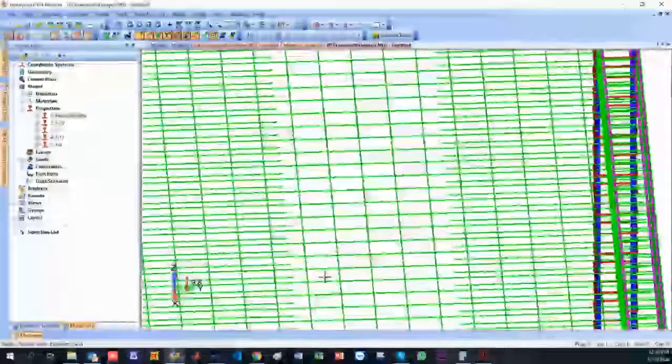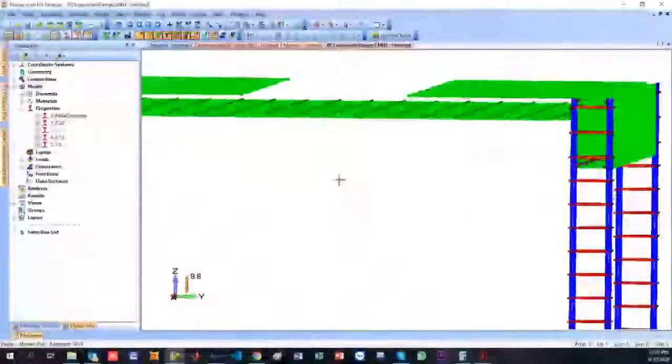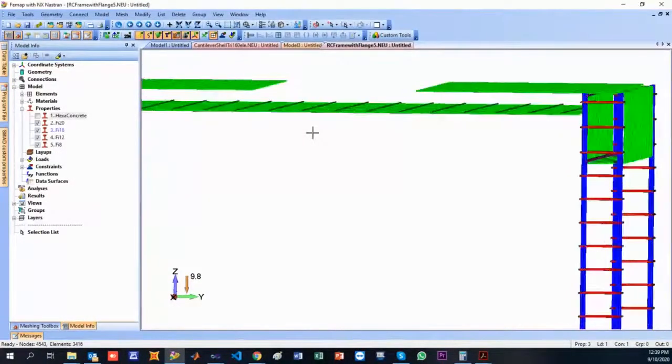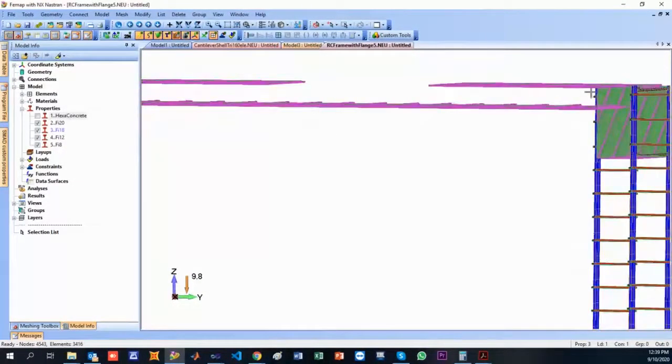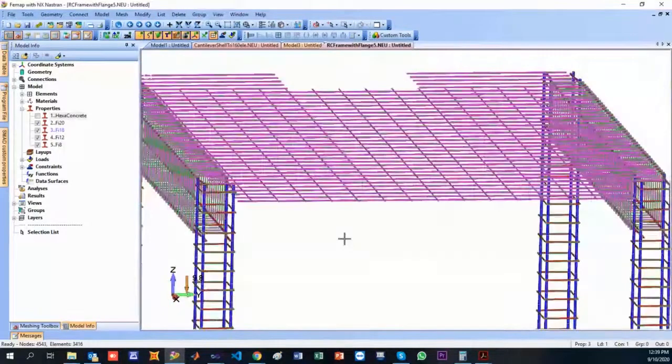If I see it from the top, I have my reinforcement along the X and along the Y. I have here top reinforcement for the negative moment, which will generate tension at the top. I'll give you a hint. There is one reinforcement which is missing in order to make this complete. Which one is it? Have you spoken about edge reinforcement?